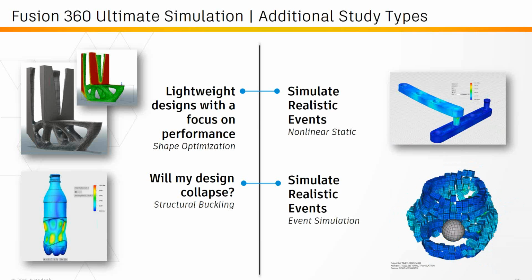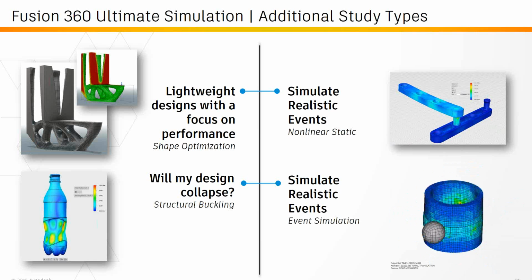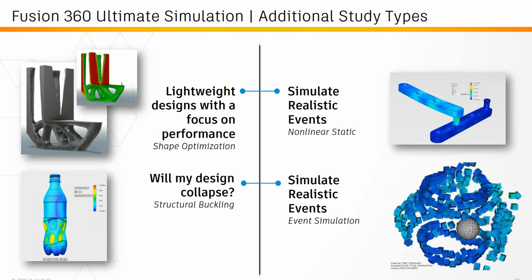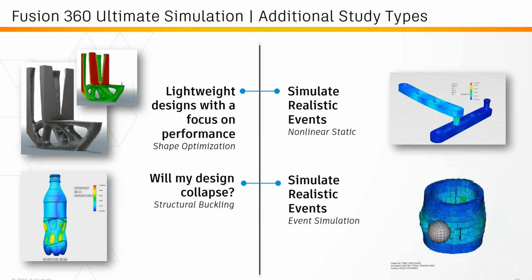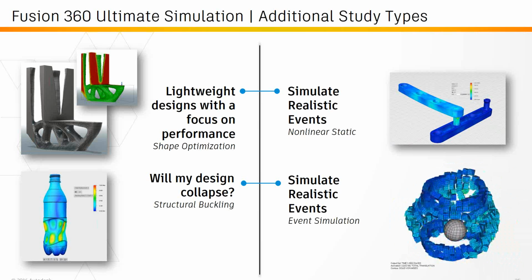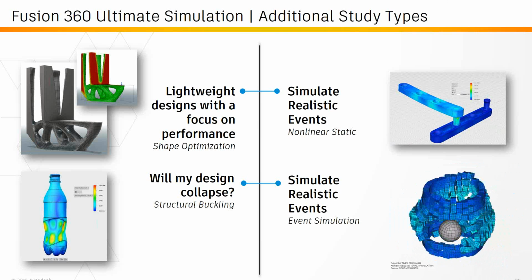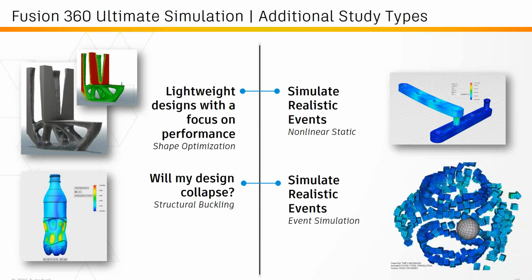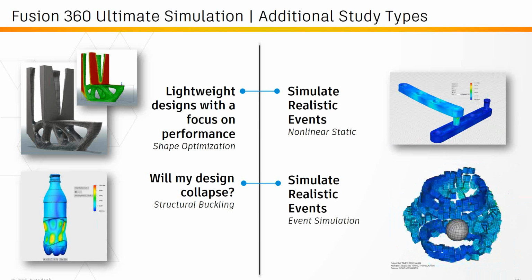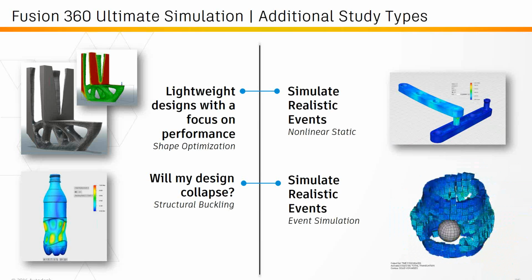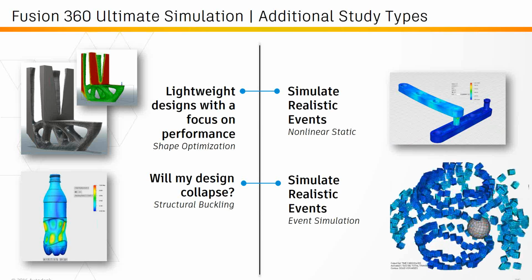And then for more realism, we can get into nonlinear statics. So essentially looking at post-yielding behavior of our structures. Maybe you're looking at what happens after I bend this thing out of shape. What level can I go to before I actually break it? Sometimes that's a valid consideration to be made, and it's actually a pretty common consideration in various applications. So you can take a look at that as well.